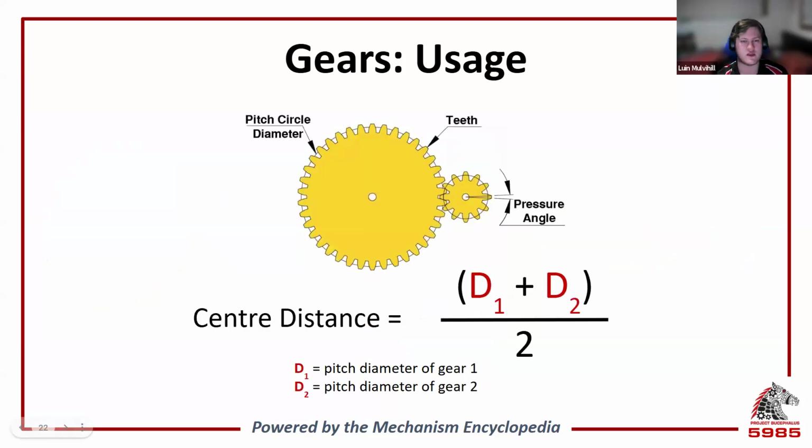For gears to work efficiently and undergo the least amount of wear, they must be located a precise distance from each other. If they're too close, the teeth rub, increasing friction, decreasing the efficiency, and increasing wear. In some cases, it'll cause the gears to jam up entirely. On the other hand, if they're too far apart, the area of contact between teeth is too small, and so the load is distributed over a smaller area. This increases the pressure on the tooth and can cause it to break off.